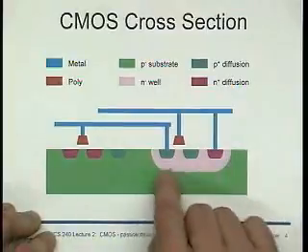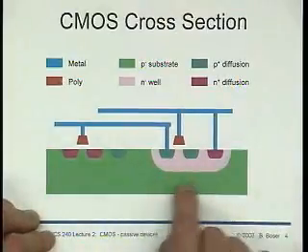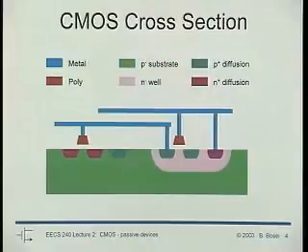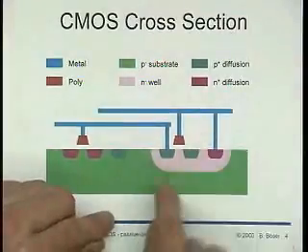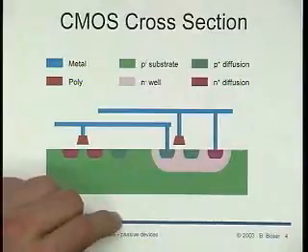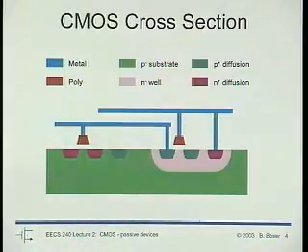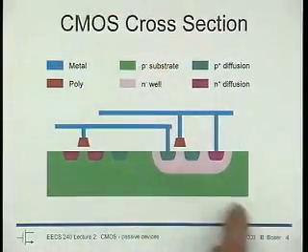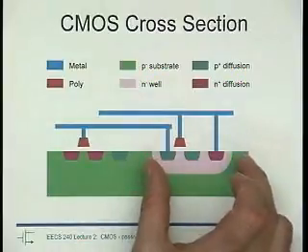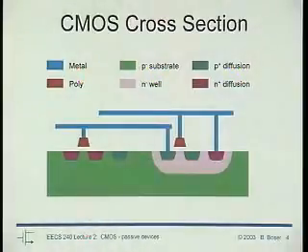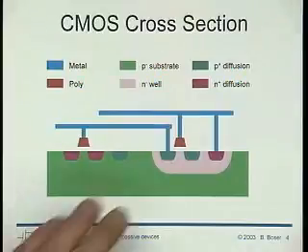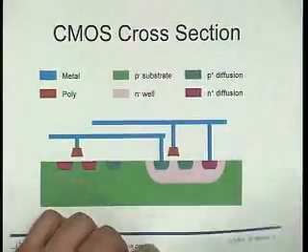Well, because SPICE says, I mean, come on, why bother? We have 20 pages worth of equations to model what's going on here. Why bother to also stick in this thing, right? So this diode isn't present. Well, it sure is present once you fab the circuit, and it sure has an opportunity to mess things up. So sometimes I draw this cross-section, look at my diode, figure out how big it is, and then stick it as an extra element into SPICE, just to be sure. Right? I will talk sometimes about this diode in this course.